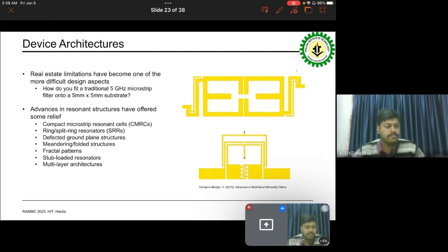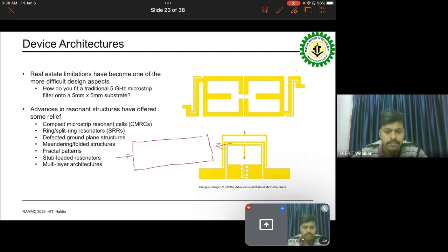One of the things I've noticed in some of the relatively recent academic journals is, if we look at the top conductive layer for our SIW, and then you'll have your transitions here and here, what I've been seeing more frequently is a set of coupled complementary split ring resonators to actually develop the filtering mechanism for these filters. And it's kind of an interesting application, because typically with the SIWs, usually your filtering mechanism will be very similar to what you see with a rectangular waveguide. And that's typically going to be an iris-based design, which I believe I've got a photo of, but just in case. So if I'm looking down the end of the waveguide, your iris-based design is going to basically clip off a portion of this, such that if I look at it longitudinally here, my poor drawing ability, but so I went into engineering. I'm not an artist.